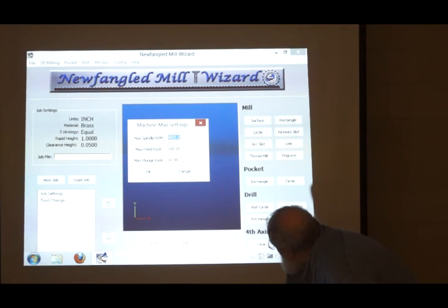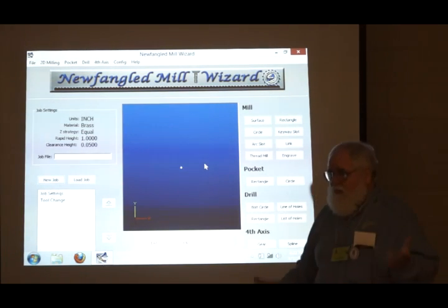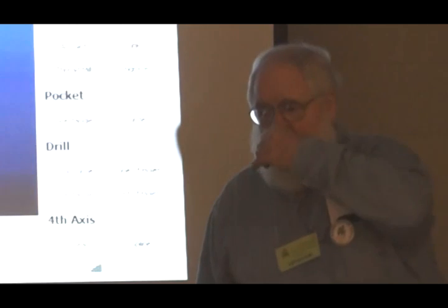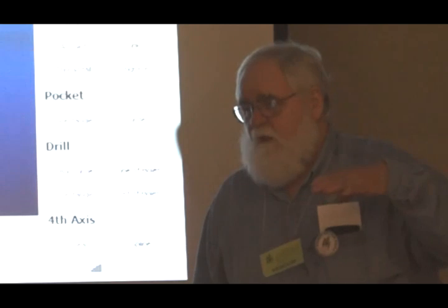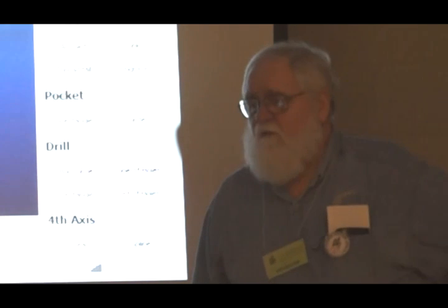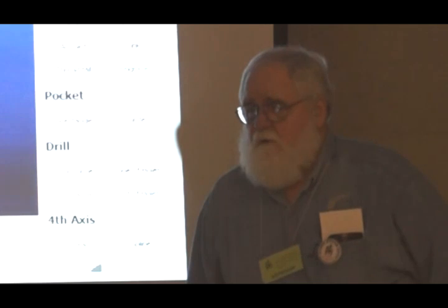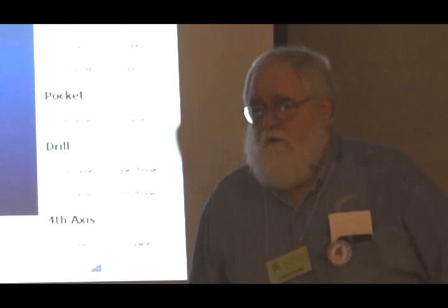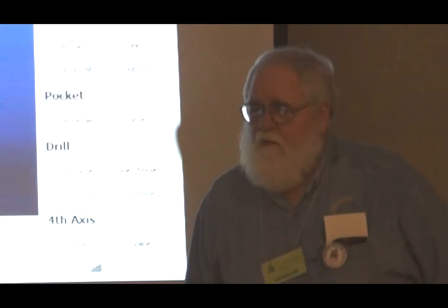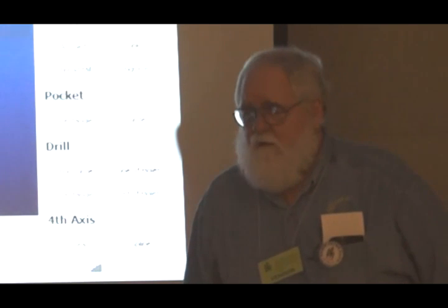Well, it adjusts to the fact that it will use the maximum speed that it's capable of doing. If the calculation wanted to go 5,000 RPM, and this number says 4,000 is all you have, then 4,000 will go in the program. But the feed rate will match the 4,000 RPM. That's right. Those numbers will all get calculated to the same. Yeah, so those all get calculated.